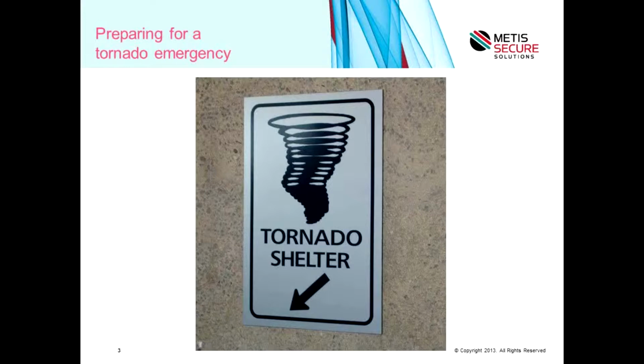While there's no place, unfortunately, in the path of a large tornado that's 100% safe, OSHA recommends a small interior room or hallway on the lowest floor possible. And the best bets are rooms constructed with reinforced concrete, brick, or block with no windows and a heavy concrete floor or roof system overhead. Avoid auditoriums, cafeterias, and gymnasiums and other buildings that have flat, wide-span roofs.